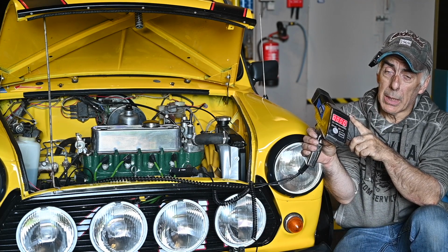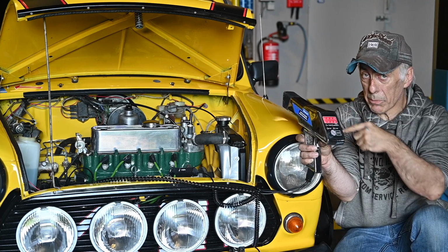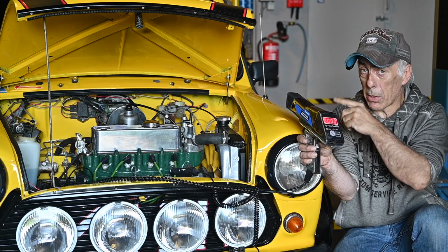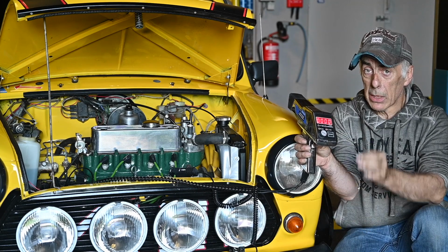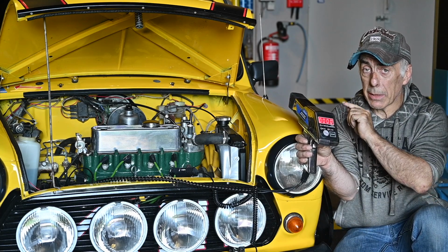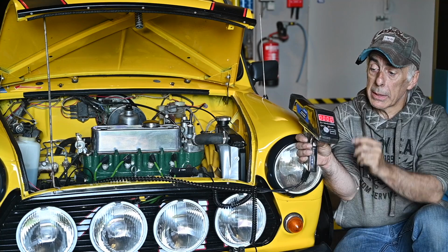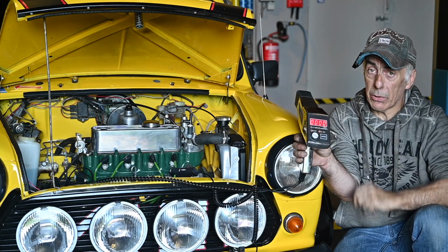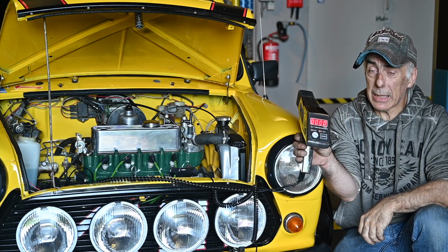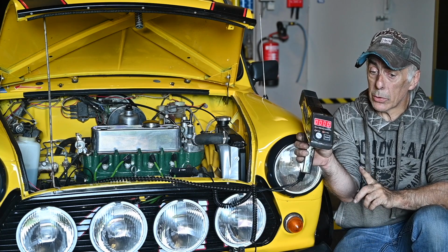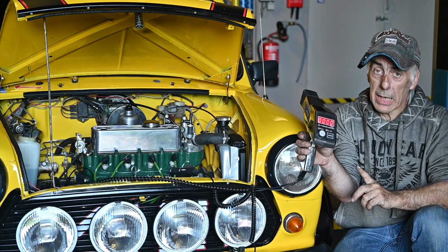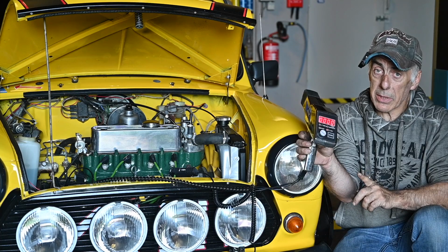So if I'm looking at this marking, I'm using the strobe light to look at where my marks are, and I'm turning this knob until my top dead center marker and the marker on my pulley line up, then I can read out the advance on this display, and then I know exactly how much advance I have. And that's a very easy and handy way to do it. So I'm going to start the engine, and I'm going to crank it up to X amount of RPMs, and I will measure it.